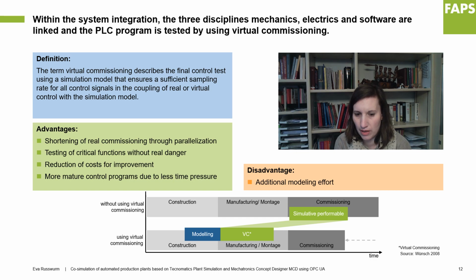In a further step, when the software engineer has already made great progress, the control program can be tested on the simulated control in the model. Compared to hardware in the loop, this has the advantage that the entire periphery, the input-output modules, does not yet have to be defined and modeled. Because if the real controller is used, it is necessary to simulate the whole periphery, with a Profibus connection, for example.